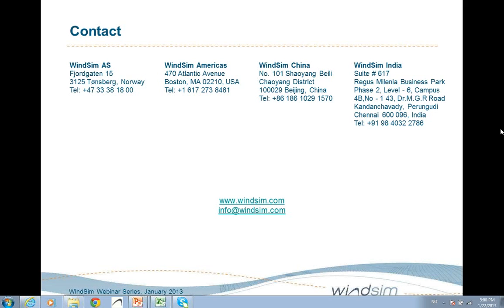Then we have a question, if I could please show again the post-processing of WindSim Express, if it is more powerful than WindSim Basic. No, it is not more powerful than WindSim Basic. In fact, when we run WindSim Express, at the moment we run the standard settings from WindSim Basic. So if you want to have more advanced settings in the post-processing, then you are invited to switch back to the full version. So set up your project in WindSim Express, and then run the wind resource and the energy module in the full version, where you have much more freedom to change settings.